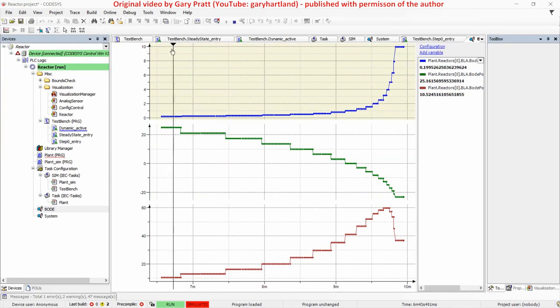Notice the phase margin is nearly zero at the low frequencies. This is the reason for the instability. But the phase margin reaches 41 degrees at the 1 Hz crossover frequency, indicating that the loop will be stable and have an underdamped transient response.